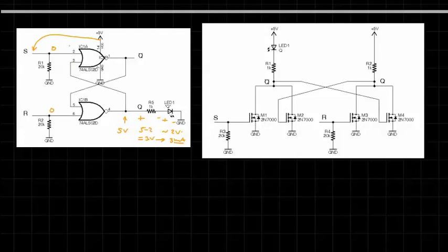If you now take your wire and connect it over to the reset, pulse it, then you should see the LED reset. Okay, that's the whole purpose of this first circuit, just for you to experience an actual sequential circuit. By the way, this is the building block for memory. So you can save a bit, 1 bit of information, in this little cell. This would be the type of memory that is referred to as static RAM. There's also what's called dynamic RAM, but this is static RAM.